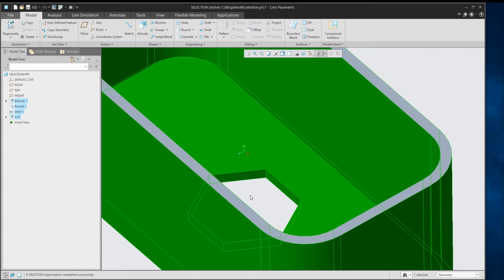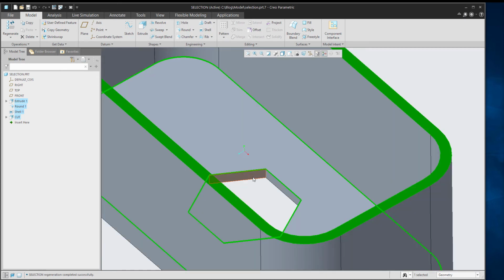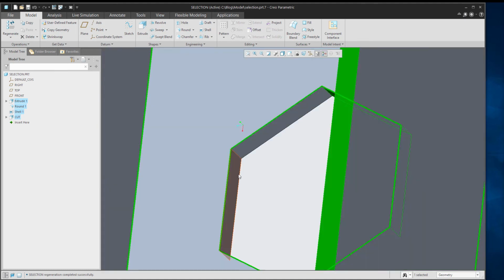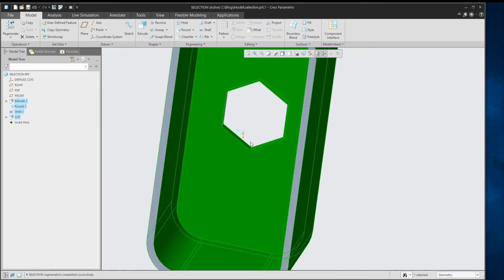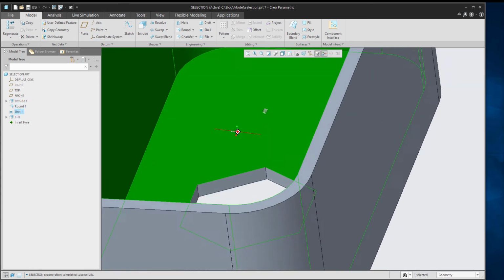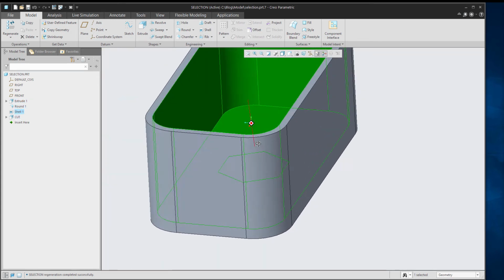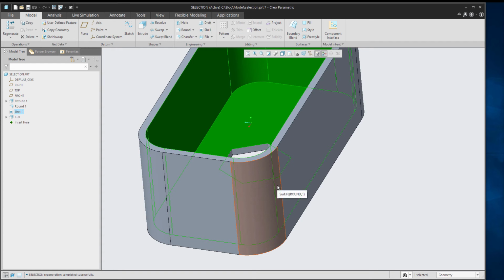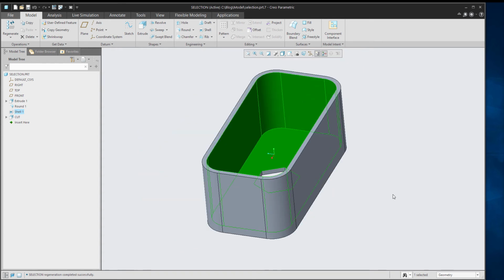All we need to do here is press the shift key back down again, and we go in and pick the surfaces that we need. So we'll grab these surfaces, and I'm just pressing shift, I'm not pressing control here. That's got me back to the inside surfaces that I wanted. All right, so that's seed and boundary selection in Creo and loop surfaces.